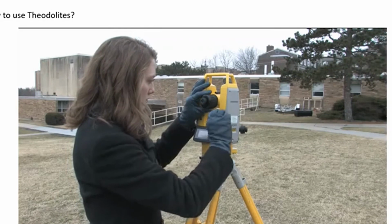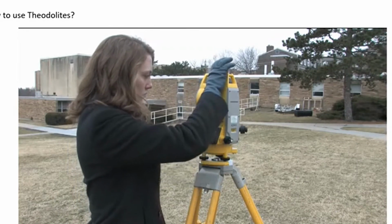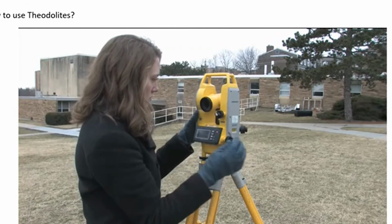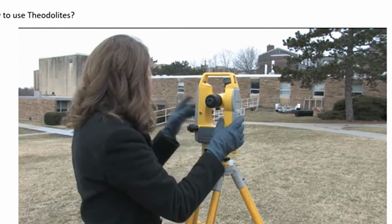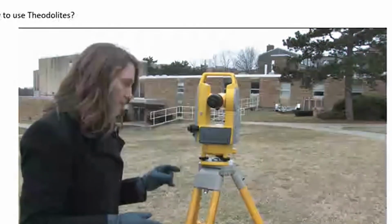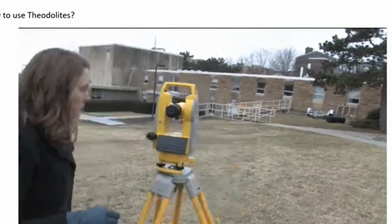Next, we will proceed to unlock the vertical angle lock and then rotate the scope 180 degrees so as to plunge the scope, and then we will unlock the horizontal angle lock and rotate the instrument so that the front of the scope is now pointed towards point A.